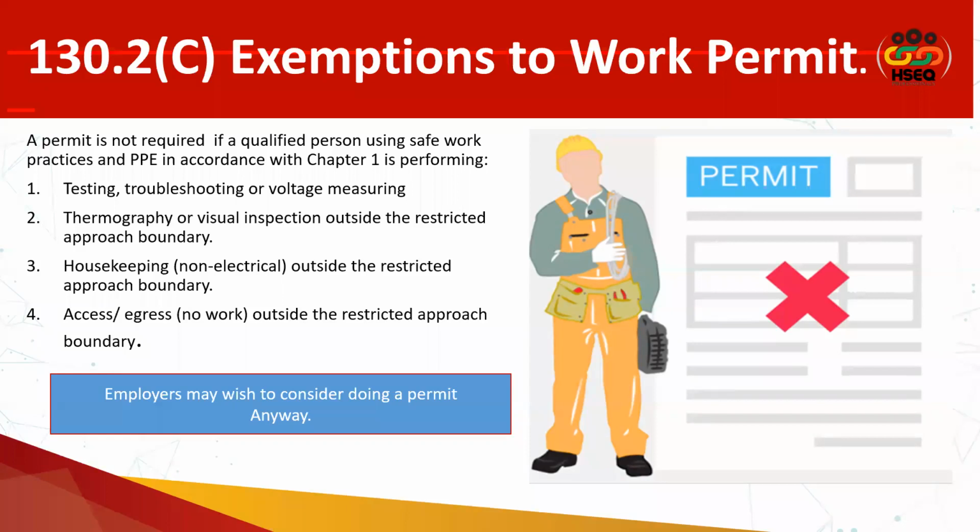Similarly, for the energized electrical work permit, don't put an exemption. Make it a mandatory requirement in your electrical safety program that you should complete an energized electrical work permit for the tasks you are performing in your organization. Right?